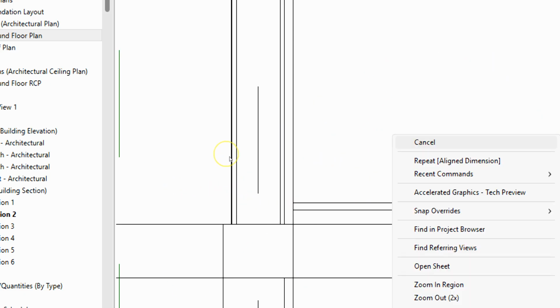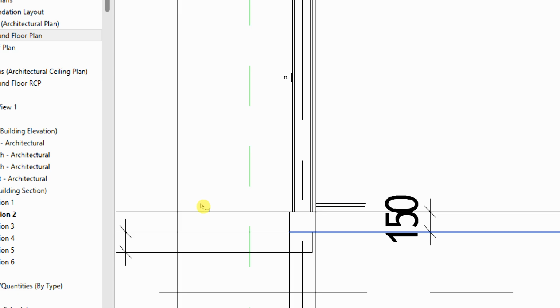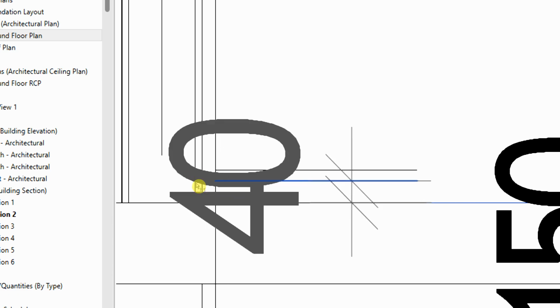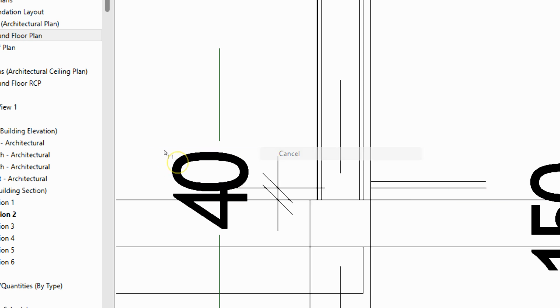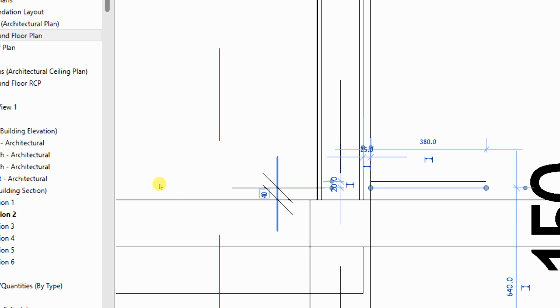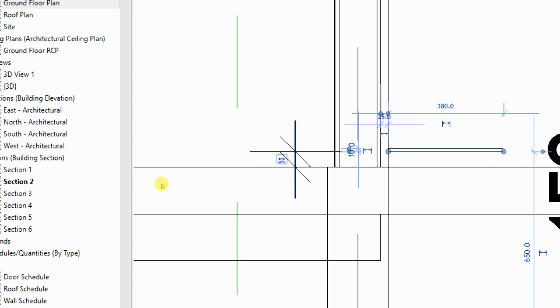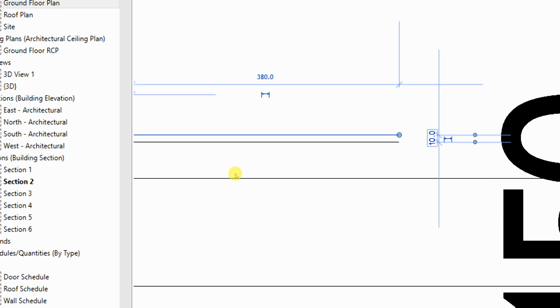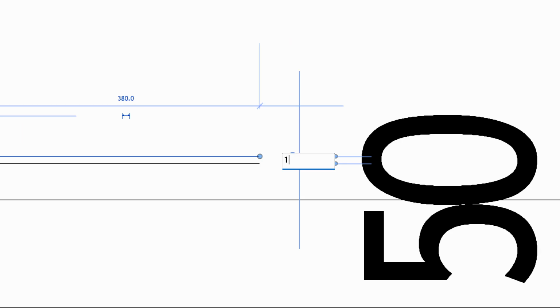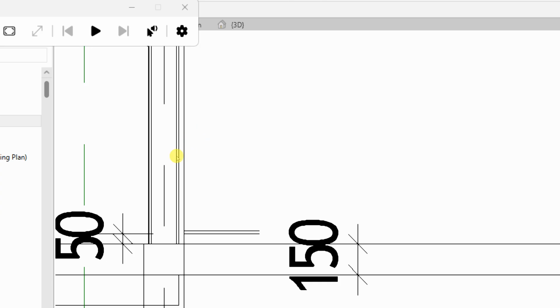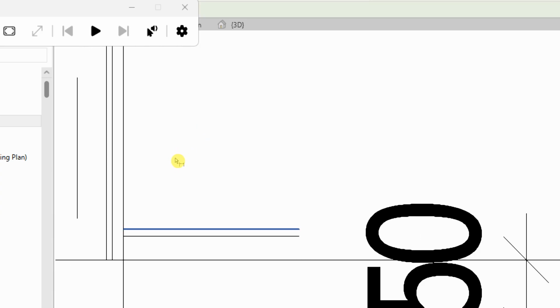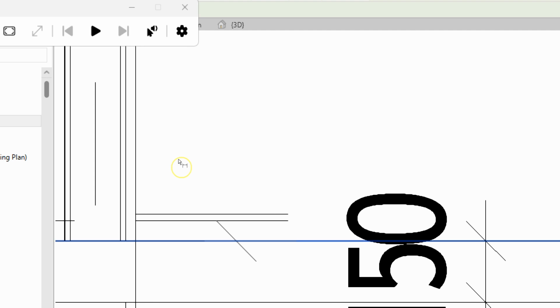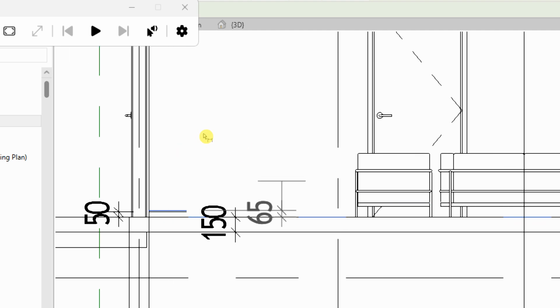So if you come in here, you see that there will be a screed. This one from here to here, let's say 50, I'll update it. This one should say 50. And then the distance between this one and this one, let's say it's 15 for the tile, including the blinding, 15 here. Now, what happens is that there is an overall thickness on top of the concrete work of about 65 mm here.